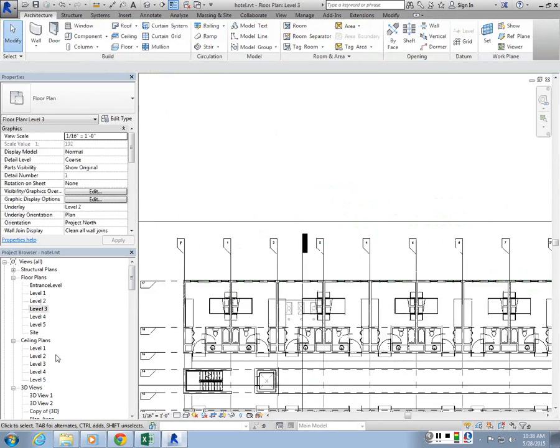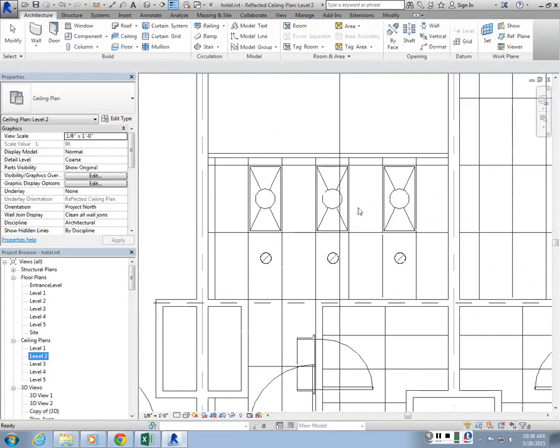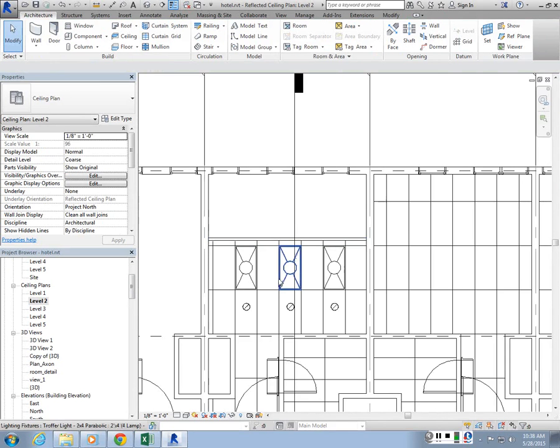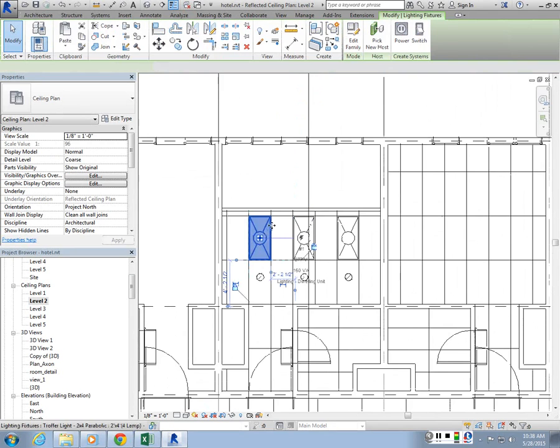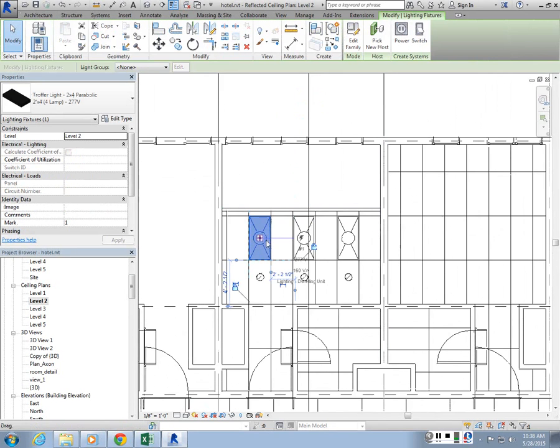Now the last thing I want to show about ceilings is that you can also create these interior lights, create arrays of them, and then put them in a group, and you can basically use them for specific renderings. You can take out or filter through the lighting groups basically. So I'm going to create a first lighting group. So I go to this room.